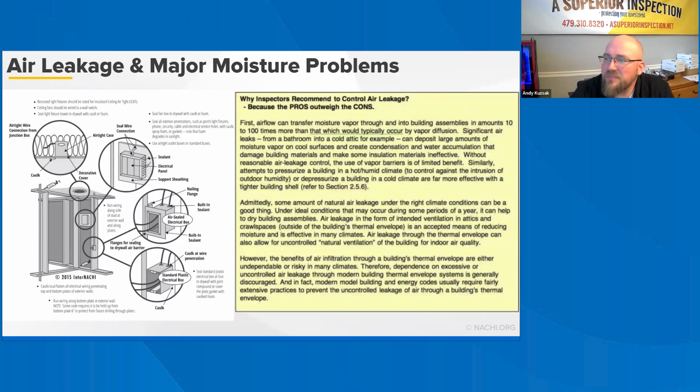Air barrier materials must manage vapor movement and water shedding based on their location within the wall. Building codes mandate air sealing around framing joints, utility penetrations, drop ceilings, and other areas to prevent air leakage. Suitable sealing materials include air barrier materials, caulks, sealants, tapes, and gaskets.